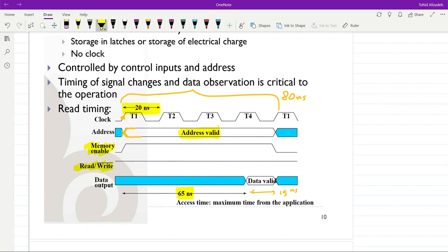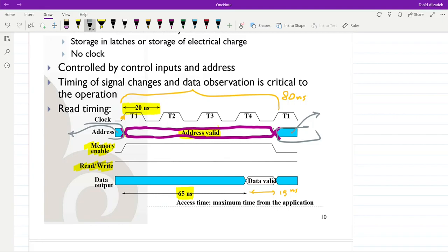Since for the address line we can have ones or zeros depending on where we are referring, you see that here we have both ones and zeros. So when we have it in this form, it means that for the address lines we may have ones or zeros. But the area shaded in blue means that the data over there is not important for now. Once it is not shaded, it means that the data in this area is important during these 4 clock passes.